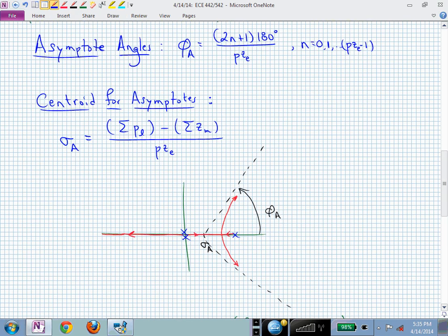Again, we'll go through an example of this, but this is a picture to get you thinking about what's happening. In that picture, what's the pole zero excess? I'm hearing 2, I'm hearing 3. Do I have a 4? You're looking at how many x's you have. That's the number of poles, which is 3. How many finite zeros do you have? There are no open zeros or open circles, so your pole zero excess is 3.